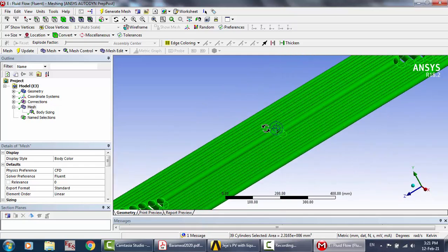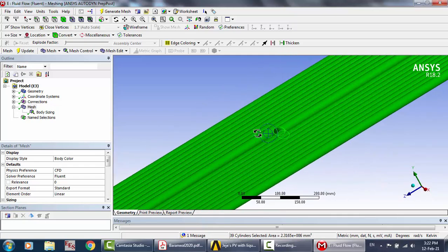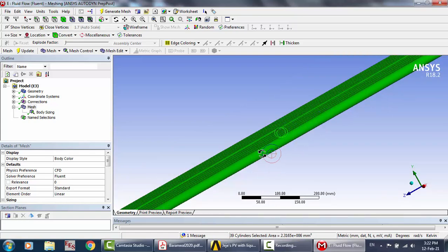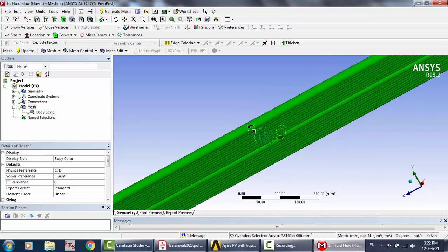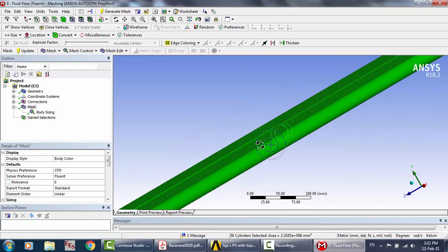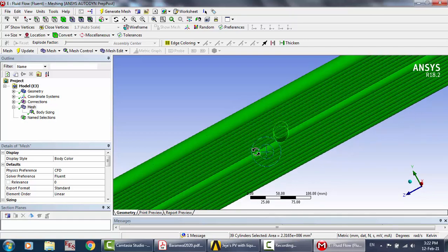But if you only wanna select the faces in direct contact with the PV, you have to split the pipe itself to be able to select the front face without selecting the back.